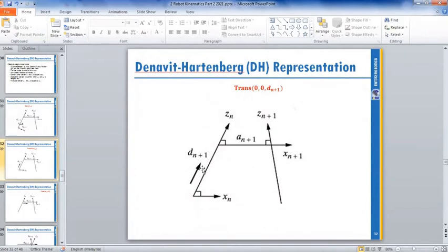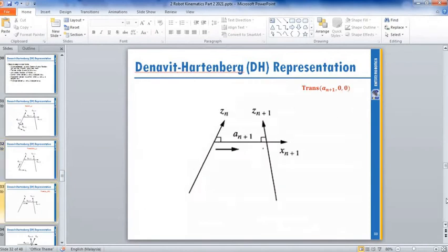Maybe your arm has a linear motion, or maybe your arm link. It depends on your robot design. You can extend or retract the arm, or maybe this d is the link length of your arm. Between these two joints you have a distance, and along the x axis we call it a. So you have a variable value for x and 0 for y and z.